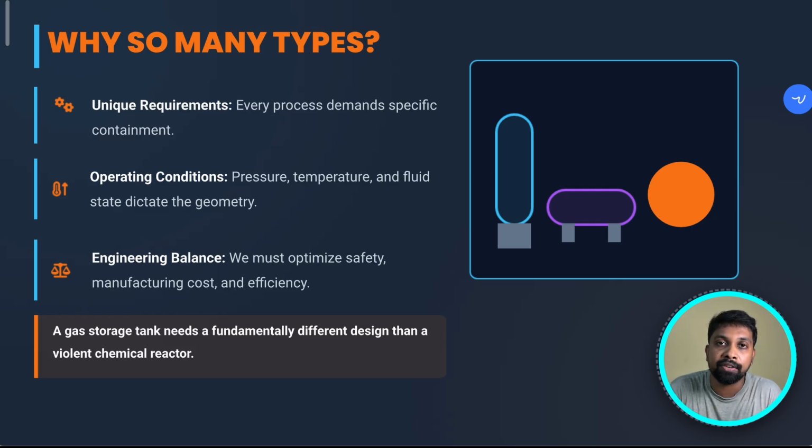If you are quoting a very high pressure vessel with a flat end or an ellipsoidal end, the head thickness is going to be huge. What a good and experienced static equipment engineer will do is choose a hemispherical head, so that he can reduce the material weight. He also needs to know whether it is feasible to form a hemispherical head in that particular location. Each and everything has to come with experience and knowledge.